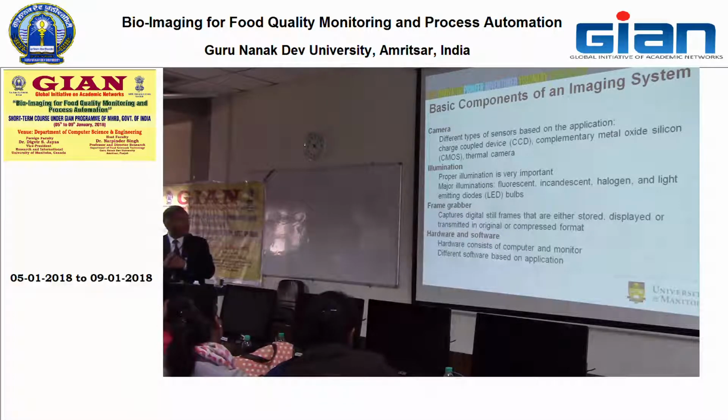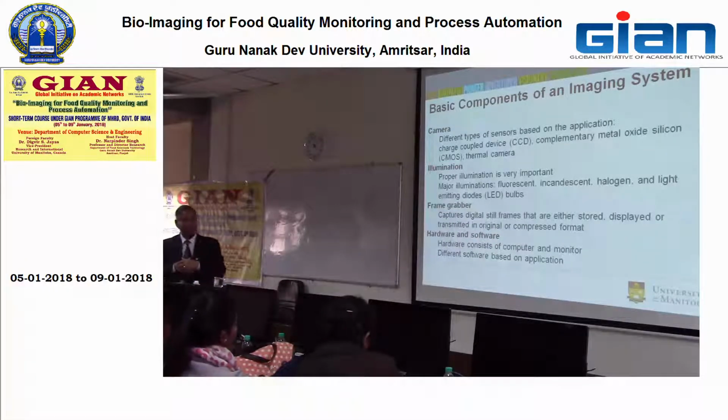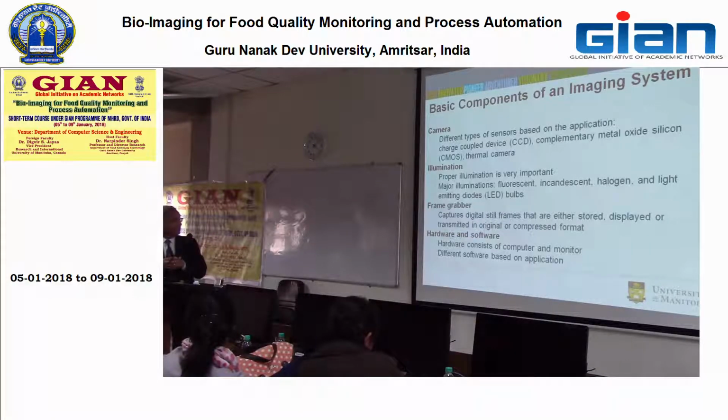Okay. The other component is the frame grabber, which captures the digital frames and then stores, displays and transmits them in original or compressed formats. Nowadays, I think the frame grabber is basically replaced, as digital cameras have built-in frame grabbers, so you get the digital images. These are very important when you are dealing with the analog signal coming from the cameras, and you have to convert them to digitized images. And then you use the hardware and software. The software is to extract those features.